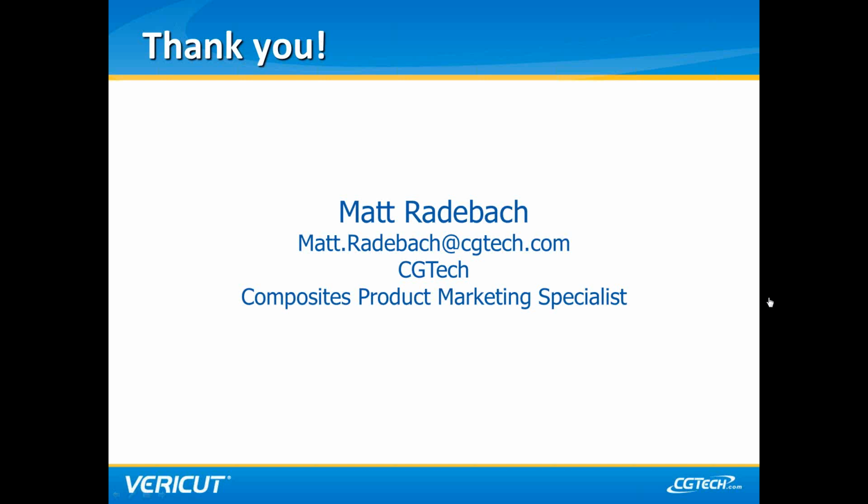All right, next question is this. You mentioned various inspection technologies such as laser scanner, FLIR, etc. that can be used. Can these technologies actually detect every single defect, and especially at the tolerances required? For aerospace parts in particular, tolerances on gaps and overlaps can be very tight. Yes, so that's where I'm not going to say every feature can be detected, because as soon as you say every feature can be detected, someone comes with a requirement that may be more challenging. For many of the standard detection requirements, I do see that these systems, whether it's one of them individually or a combination of the units, you would be able to get what you need. Now, of course, if you're looking at trying to have tolerances on, I don't know, the micron level, it might be more challenging, but for standard inspection, I'd say yes.